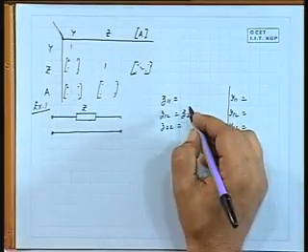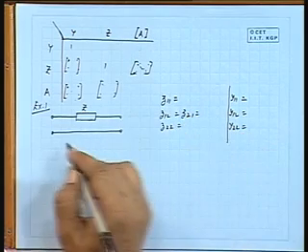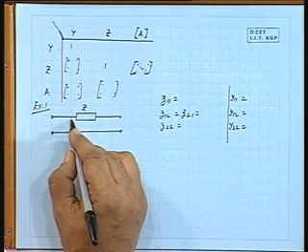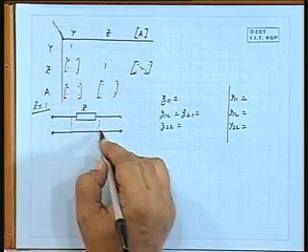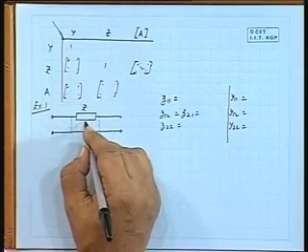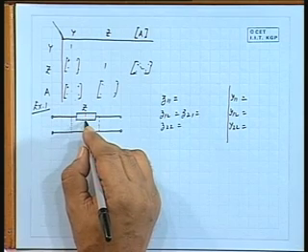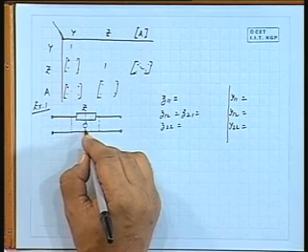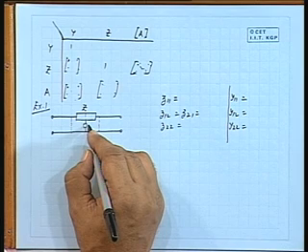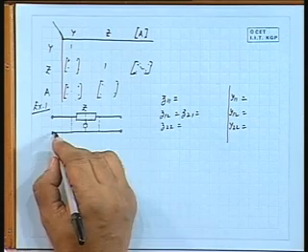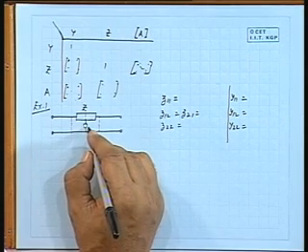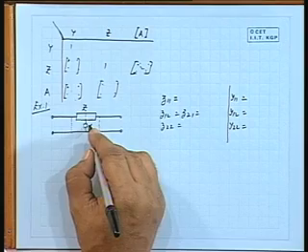Now, let us see what will be Z11. We will be completing this network either in terms of a pi or a T. For Z, it is convenient to go for a T network. So, I will break it up into two halves and then I will put one impedance here whose value is infinity, as if the midpoint has been connected to the ground, to this reference line, by an infinite impedance.